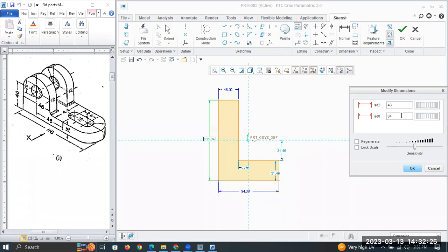You will rotate. Of course, you can rotate, no problem. But see, only thing is here already the wedges are the same, whose lengths are the same. Just now I broke the constraint. Is that clear? L1 I have deleted. Okay. See, there are n number of ways to produce this. So here I am following this one. Okay. So only this value is 64. Then the total horizontal length of this profile is how much? 118. Then this wedge is again 16. Now this I am not going to worry about. Is that clear? This I am not going to worry about.